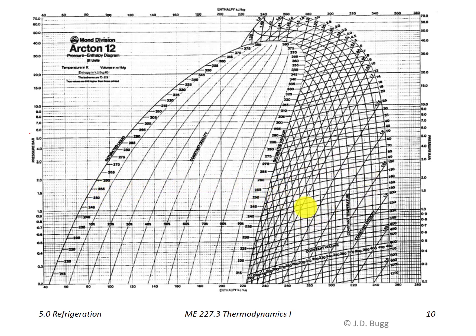In the vapor region out here, these are the lines of constant temperature tailing downwards like this. These steeper lines heading up like that are lines of constant entropy. So those are the most important lines, but this one also has lines of constant specific volume angling up this way. We don't really use those in this course, however. So that's just a look at a pH diagram actually drawn to scale.